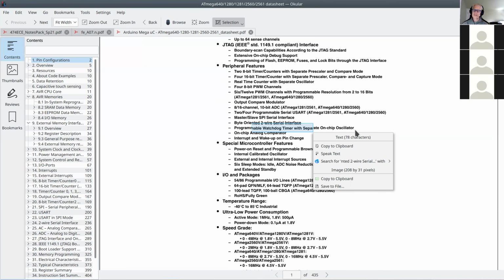If your software is dead or locked or in an infinite loop, it's not able to respond to the timer. And the timer knows that if it does not get reset within a certain amount of time, it will send a hard reset to the entire system and reboot the chip.